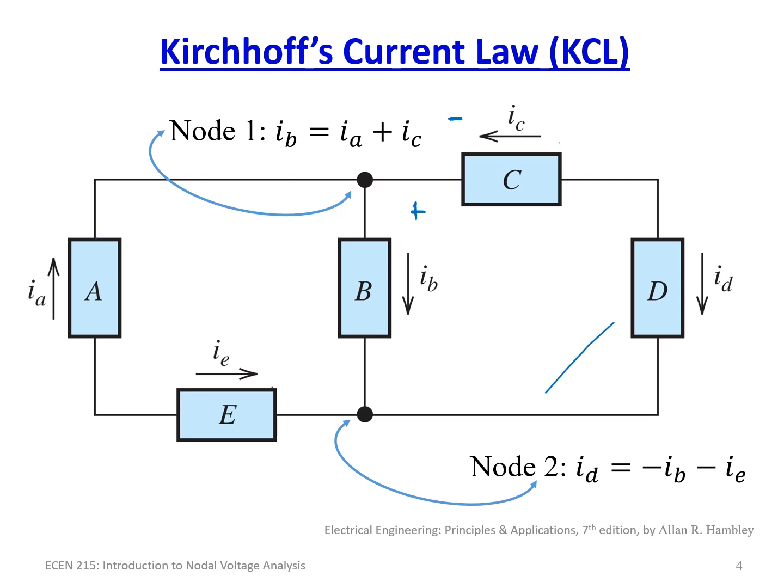So again, let's just look at element B. So we'll set the direction following the arrow. Again, we're assuming everything here are resistors, so RB. So IB, and being a resistor, it goes in the direction of the arrow. Since this is an absorbing device, that means the current entering the positive terminal to negative terminal causes a voltage from positive to negative. So that's what we're doing here. So again, IB is equal to VB over RB.